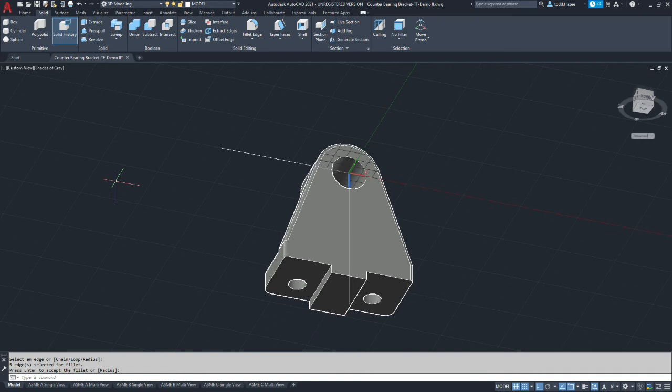So we're done putting rounds and fillets on this part, and I would encourage you that even if you can't get all the fillets just quite right, if you're able to generate geometry that will generate the proper views you need on the drawing aspects, that's what's most important for this class.